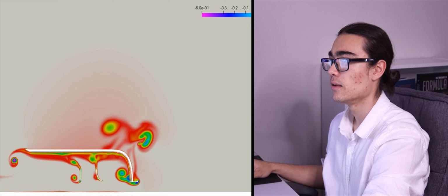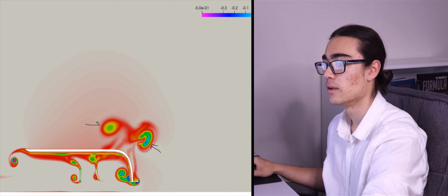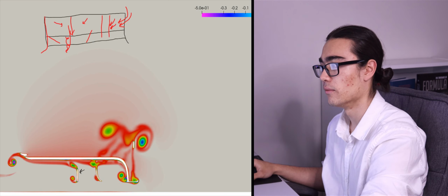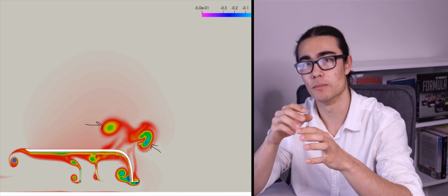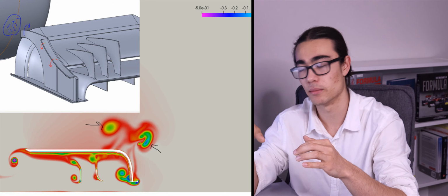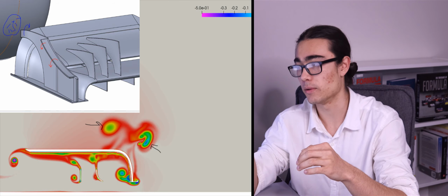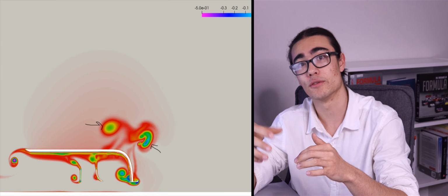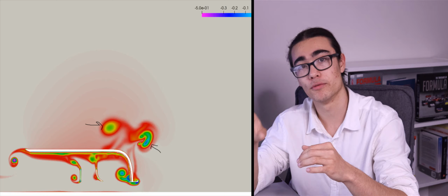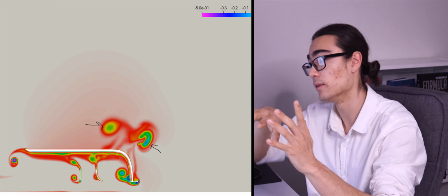So we can begin to see some of the interaction between this vortex and this one here. Now you will notice that the canard vortex there has gotten quite lossy. I think that's because of maybe the M plate vortex. I haven't done sweeps in my report detailed enough in my script, but I think that that'll be from maybe the back side of the M plate, or potentially some sharp edges which are flicking up a little bit of loss, and we're losing some performance there. Regardless, we're still going to see the interaction that I wanted to see.